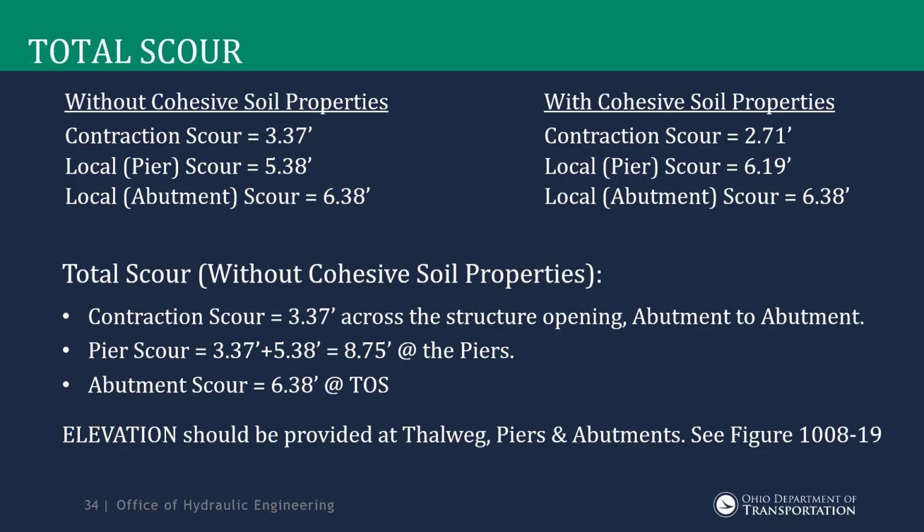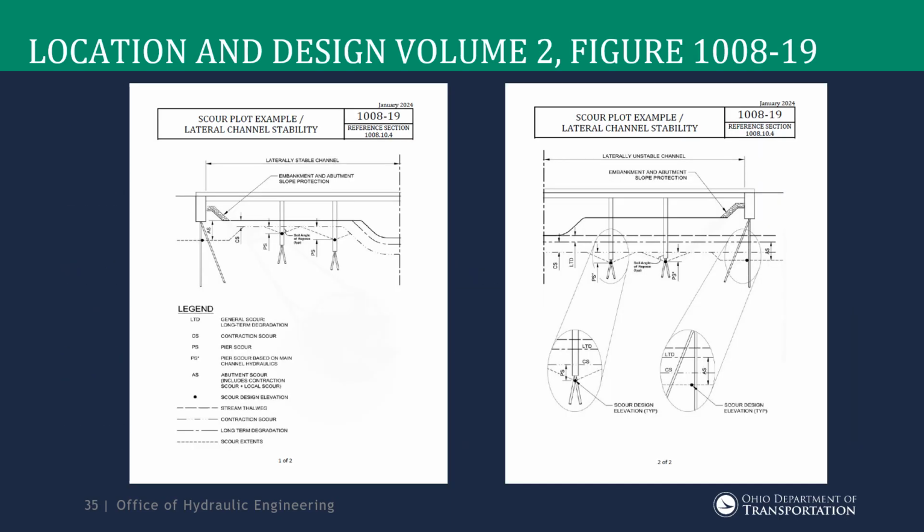We want, and the bridge people and the foundation people want a scour elevation. So you should take that depth and apply it and provide an elevation so that the foundation people know how far down and at what elevation the scour does occur.